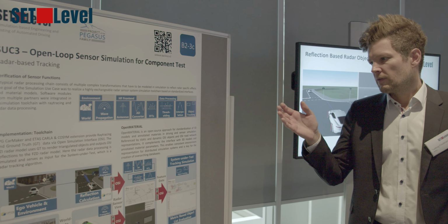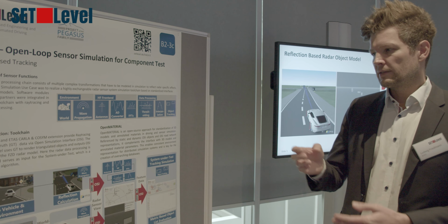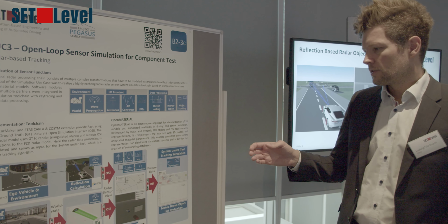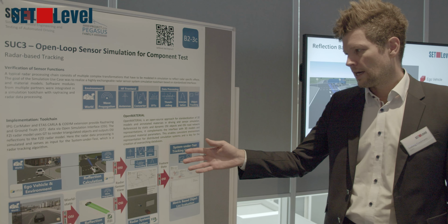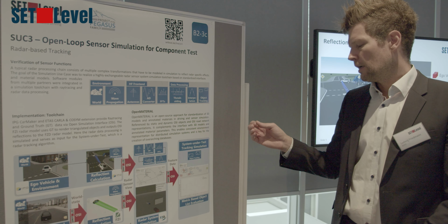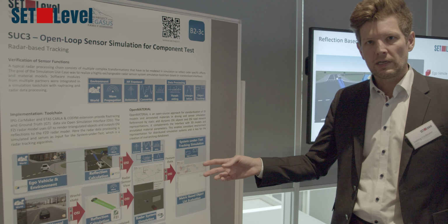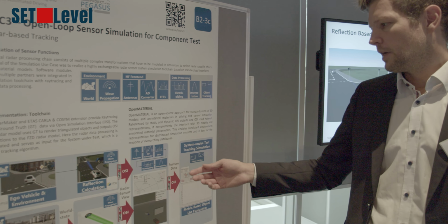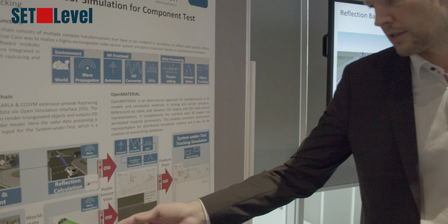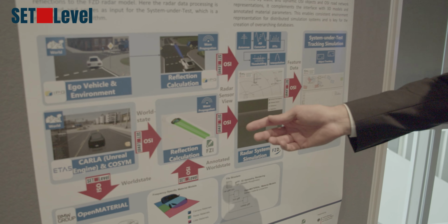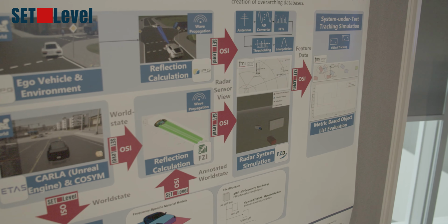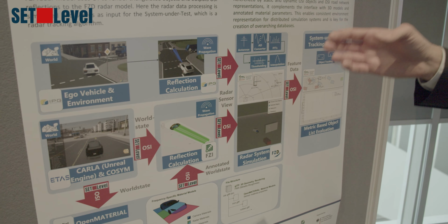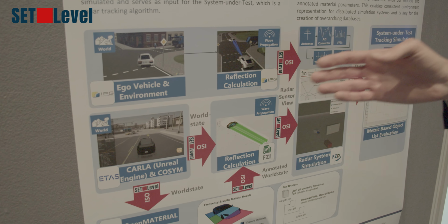To do so, we developed a modular toolchain comprising two different environment simulations. We enriched those environment simulations with OSI interfaces in order to interconnect two different radar sensor models, an object-based sensor model from FZD, as well as a reflection-based radar model from FZI. And in order to create a consistent virtual world in the reflection-based radar model of FZI, we enriched the OSI